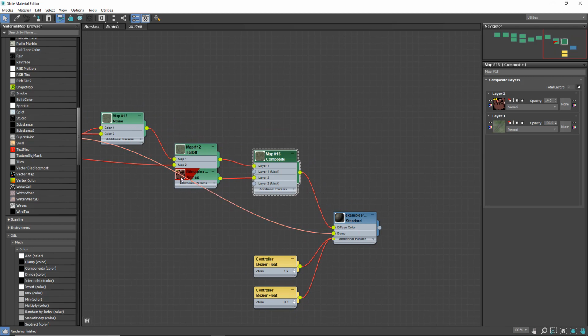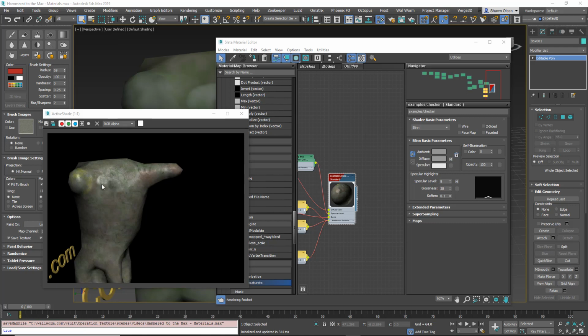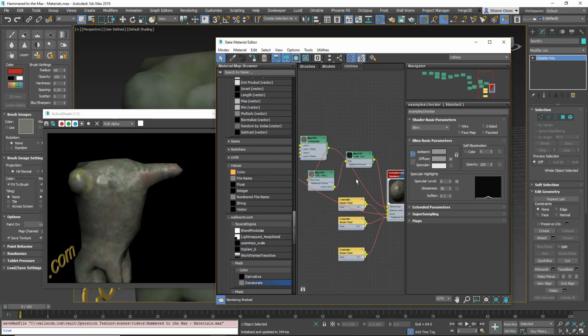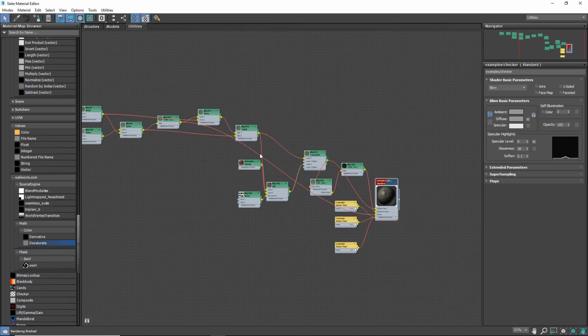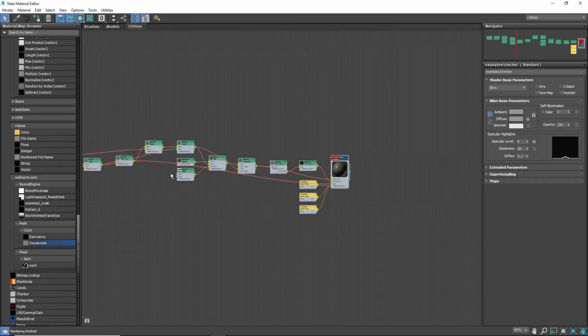And that's where the unwrapping we did earlier is used for. Also for our painting purposes, you can see we painted onto this into the unwrap channel that we had done. So I did a little bit more tweaking to fade out the material, to fade the painted layer more like it's more deteriorated. So now I want to bake this into a version that can go into the game engine, because again, this, I'm going to hit C here to lay these out. This bitmap or this shader tree cannot go into the game engine because all these procedural textures, those don't translate. So we need to bake it into bitmaps.